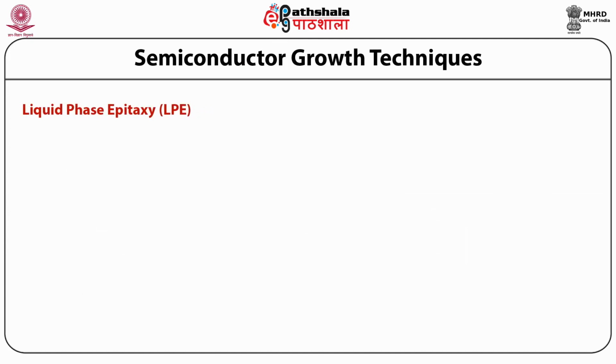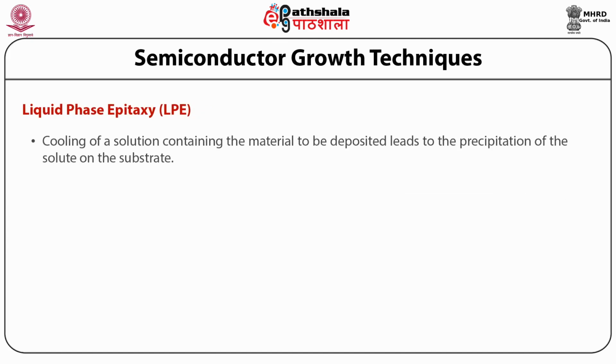Liquid phase epitaxy (LPE). Cooling of a solution containing the material to be deposited leads to the precipitation of the solute on the substrate. The system is cooled below the saturation temperature.